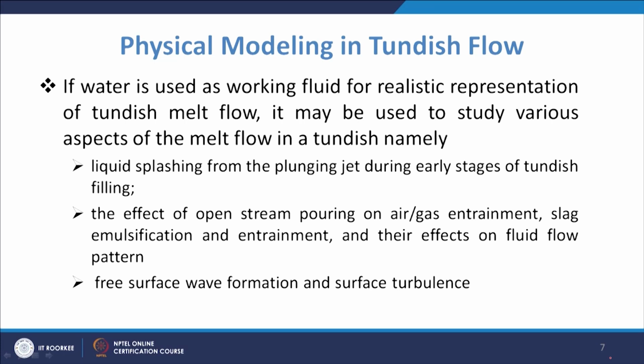If we talk about physical modeling in the tundish, as we discussed, we are using water as the working fluid for the realistic representation of tundish melt flow. When we use this water, we can use it for studying various aspects of the melt flow. These aspects are, for example, liquid splashing from the plunging jet during early stages of tundish filling. You will have the plunging jet coming in and then there will be liquid splashing. So, that can be studied.